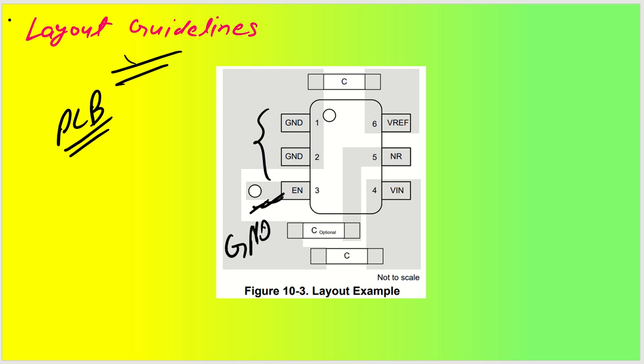You don't connect the capacitor here, otherwise there will be a problem, a very big loop will be there, so this is not recommended. So connect the capacitor like this. Then, sorry, this is my input capacitor, so the input capacitor will be like this.